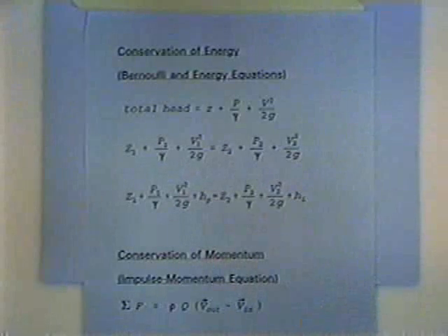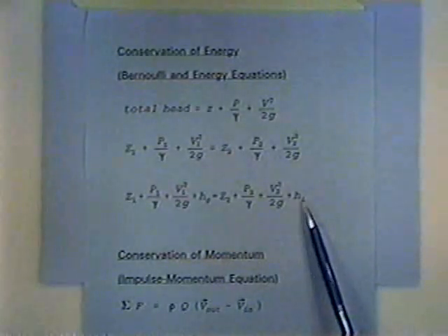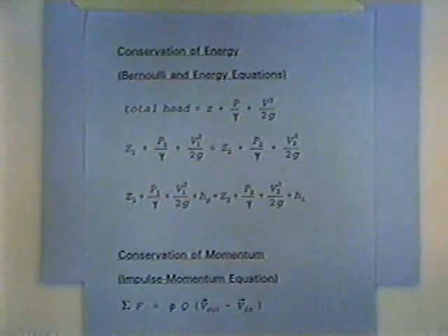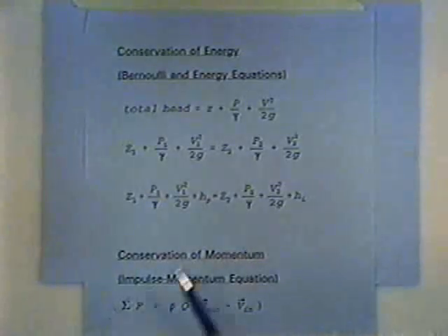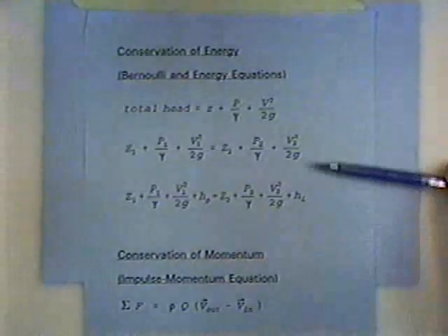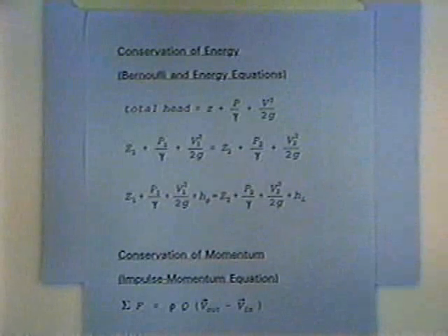Except this is not quite true, because we really don't conserve energy. We lose energy, or at least we lose hydraulic energy, as it is converted to heat and lost to the environment. So we have a head loss term, and we'll spend quite a bit of time next week dealing with it. We can also add energy to the system by a pump, so we have a head added by the pump term.